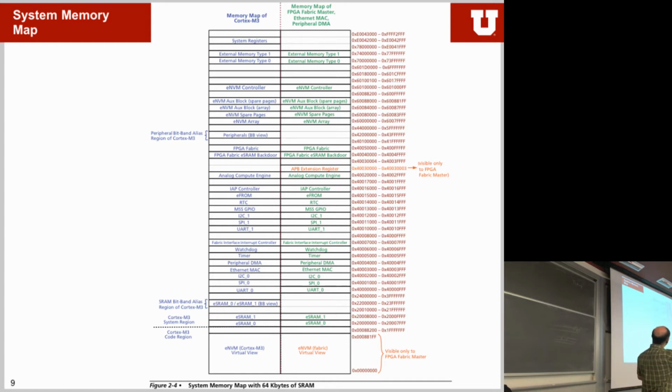If you have an address in the peripheral bitband alias, these aliases point to memory locations in the peripheral section. So the peripheral sections are all down here. This is the bitband area for it. So if you want to read up on details on that, search for bitband on ARM Cortex M3s, and it will tell you what this particular case is. In the SmartFusion documentation, that's where they talk about it.